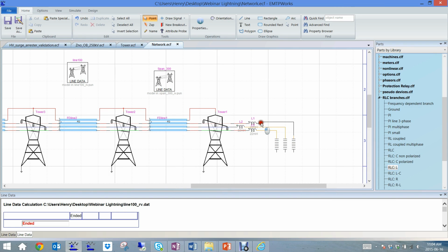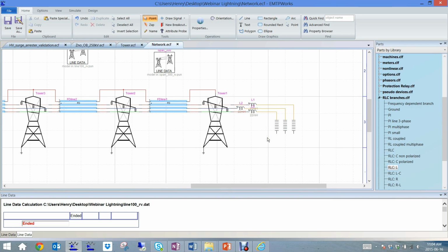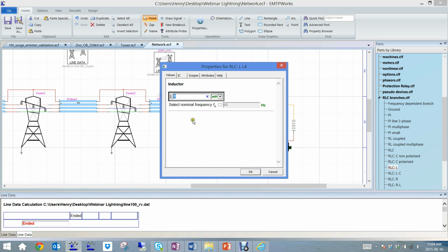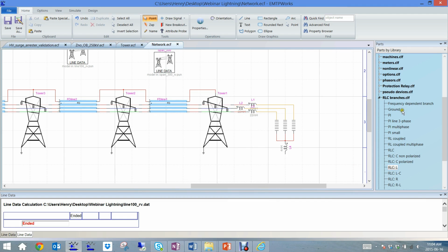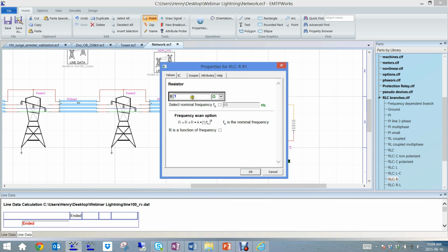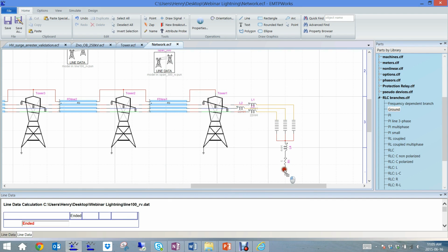Here you go. And actually, you can also model the way they are grounded. So for example, if they are grounded through a cable, then you have to model that as well. So you connect all of them here. Then let's say you have a small cable of a few meters. And then you can ground them through the resistance of the substation. If you know the grounded resistance, all those details don't make a big difference, but if you have this information, you're always better to put them in. So here the grounded resistance of the substation, let's say, is 5 ohm.